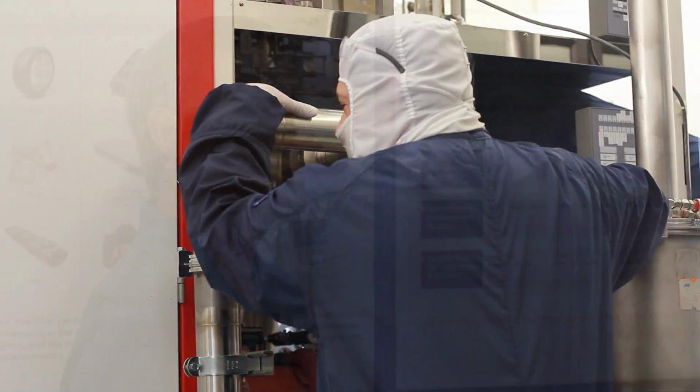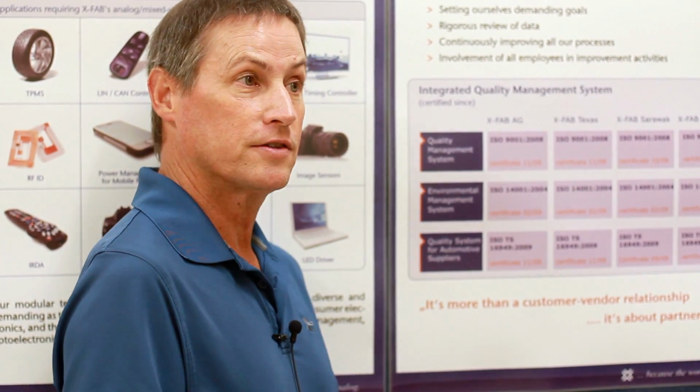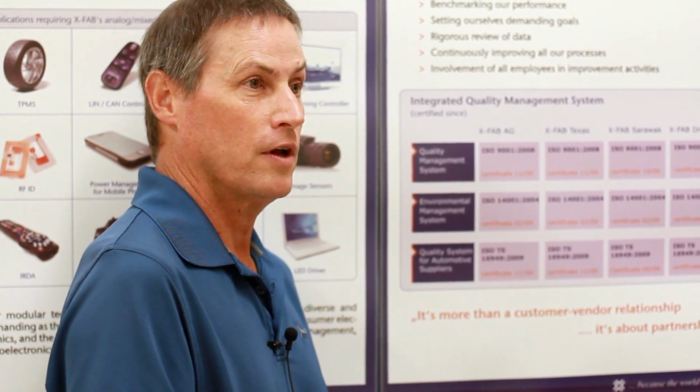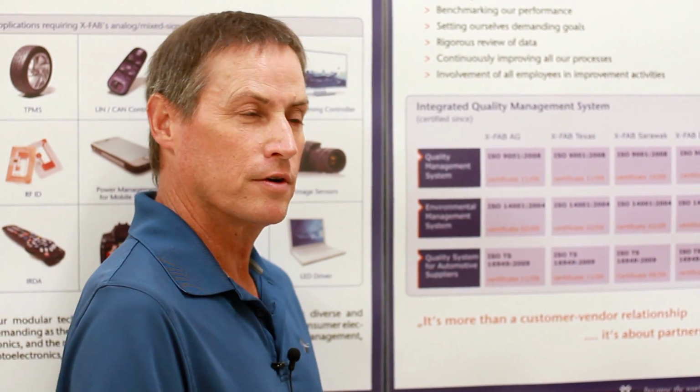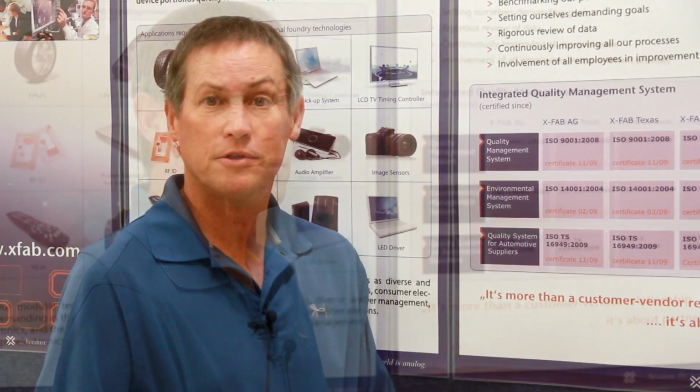within the car. So we typically run our manufacturing in lot sizes that contain 25 6-inch wafers. And those lots run through, in a typical process, about 300 steps to complete the integrated circuit. And at any given time, we'll have as many as 100 different process routings that are running inside the factory and thousands of wafers of inventory.